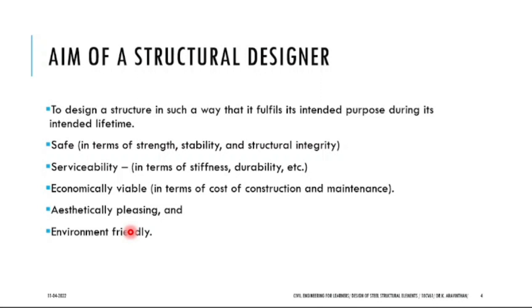But when considering the environmental aspect, how are red bricks manufactured? They use clay, the red soil, and make it into a brick. While manufacturing a brick, you burn it to 1500 degrees, yes or no? So when heating that, the environment also gets disturbed. So if you go for fly ash bricks, what happens? Fly ash is a waste material, yes or no? Fly ash is a byproduct. So by using the byproduct, you are making a material.